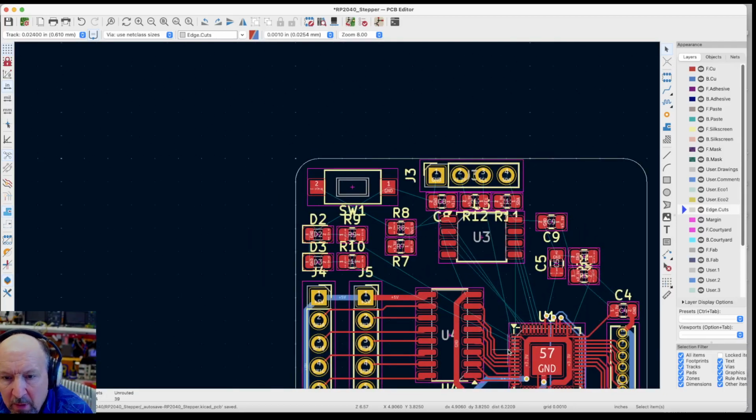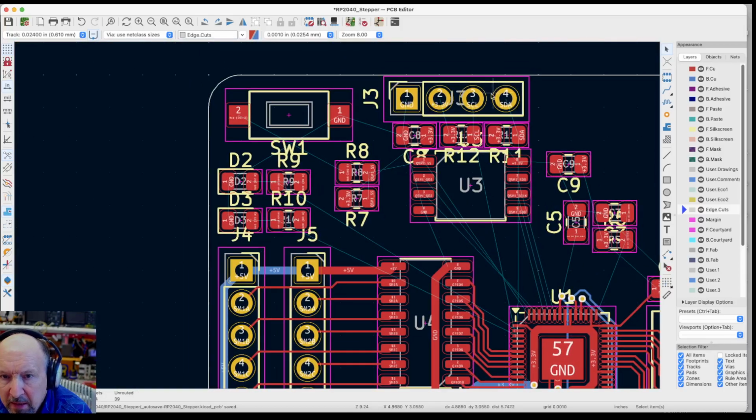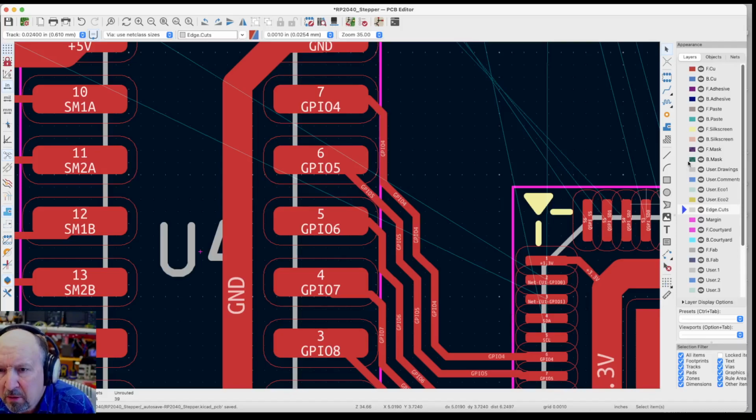Okay, so next up I want to get these SCL and SDA lines connected. This connector is through hole, so everything is on both sides of the board. So if I can just run the trace on the blue layer, straight down, put them on vias, and put them in. I wonder if I'll get myself in trouble. Let's try that.